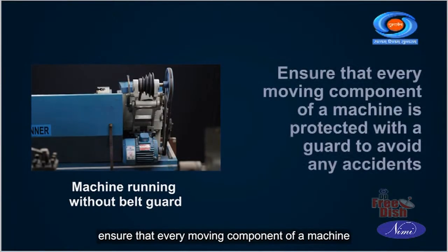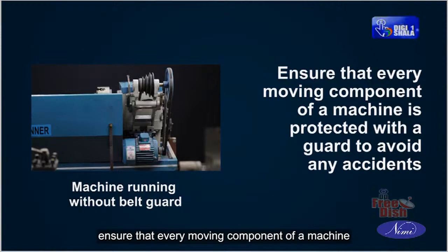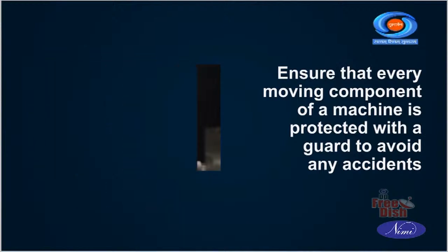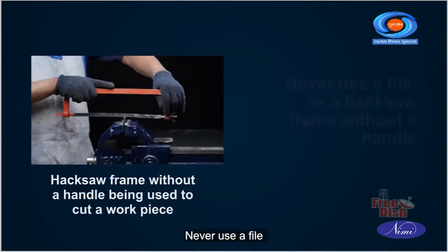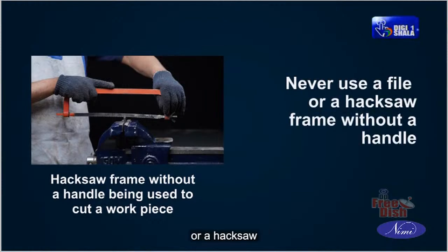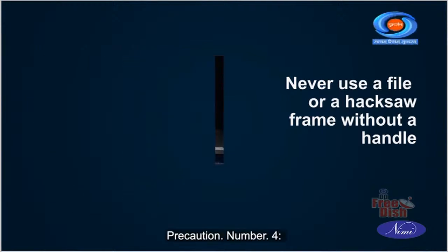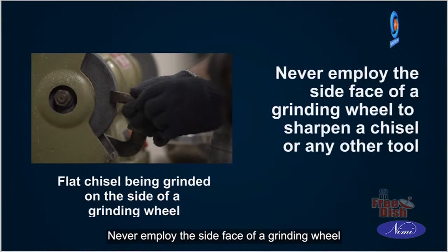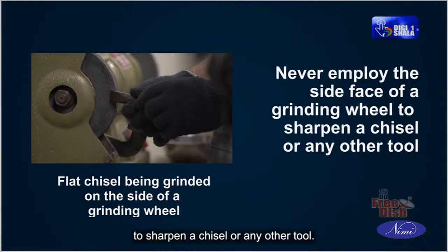Ensure that every moving component of a machine is protected with a guard to avoid any accidents. Precaution number 3. Never use a file or a hacksaw frame without a handle. Precaution number 4. Never employ the side face of a grinding wheel to sharpen a chisel or any other tool.